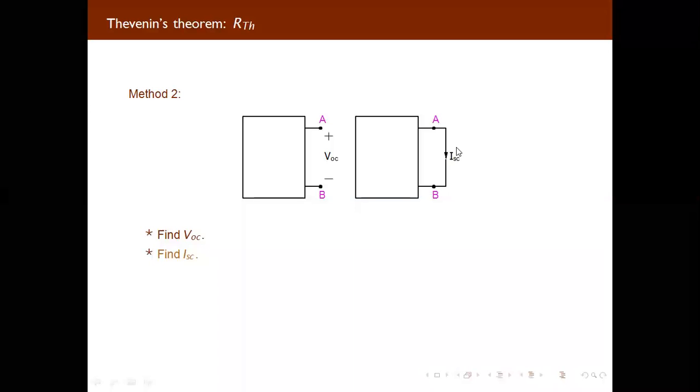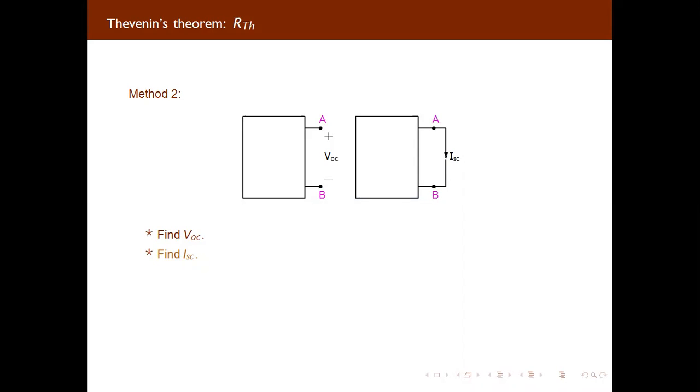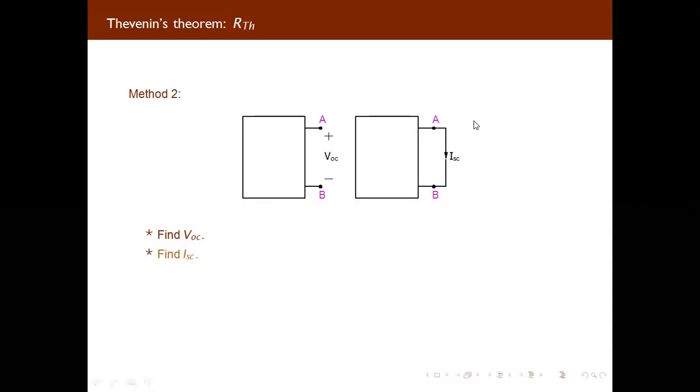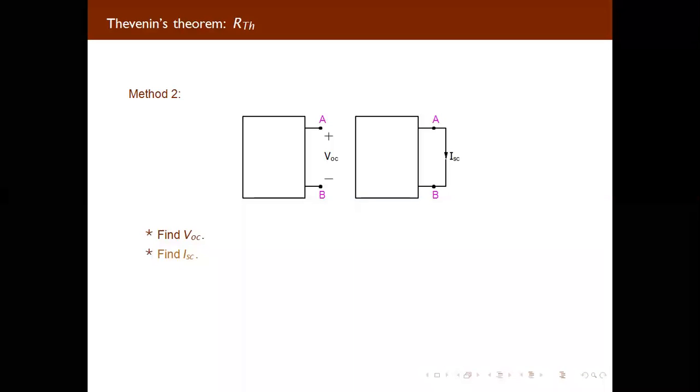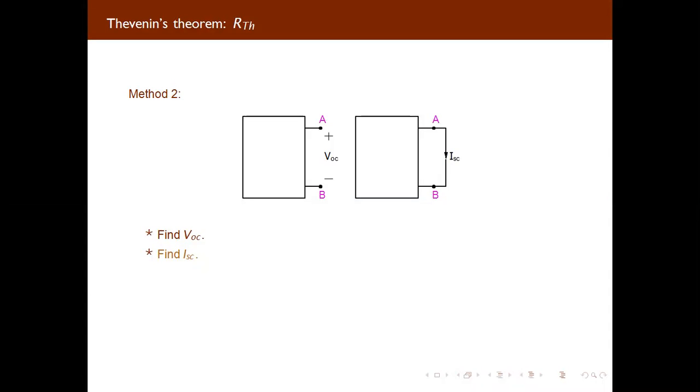We are calling this network a Norton's network. So what is the change between Norton's and Thevenin? In Thevenin we get a voltage and a resistance, the circuit is open, and the resistor is in series with the voltage. We can convert that circuit into a current source. How? The current source will be in parallel with the resistor. That resistance will be exactly the same as the Thevenin equivalent resistance. But here the circuit is just parallel, and here it is a closed circuit.